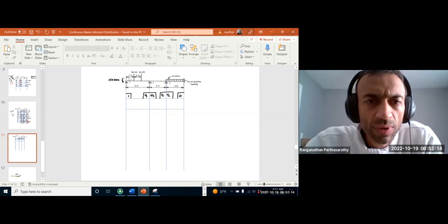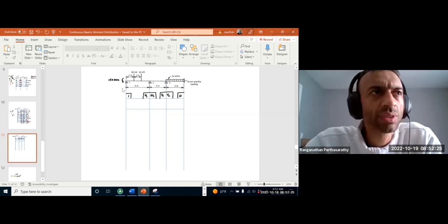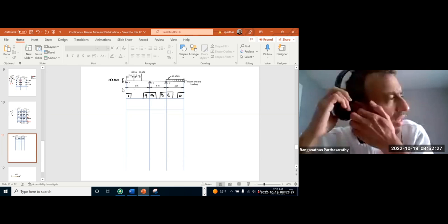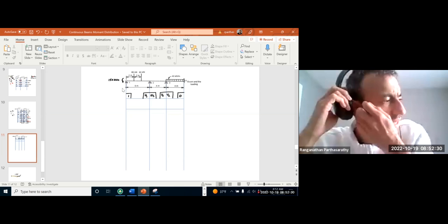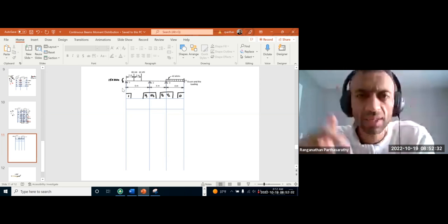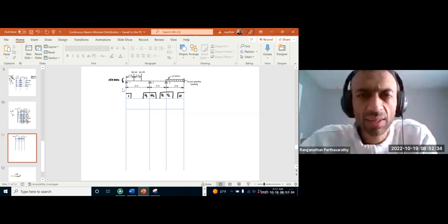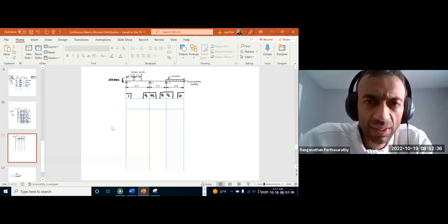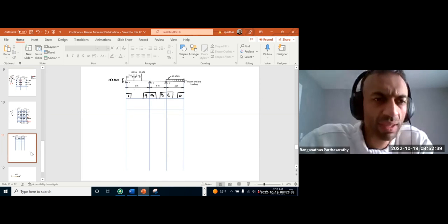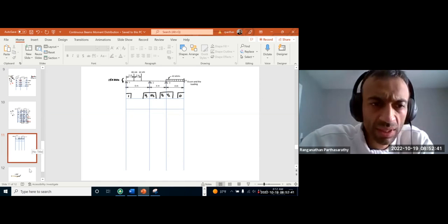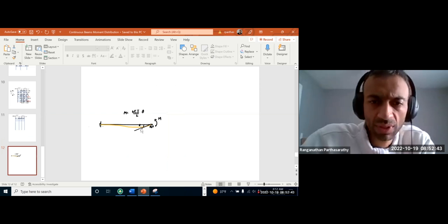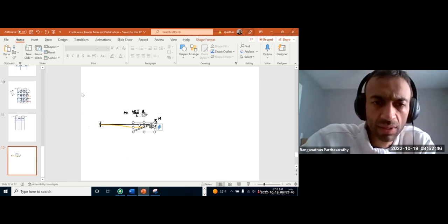Over here, we are taking this as a pinned end. So when we apply 80-80, that is for the fixed case. Since we are not taking this end as fixed but as pinned, it is better that we adjust in the first step itself. Instead of fixed, we take it for fixed-pin. So let's do that in a separate case and then put those numbers. That will be easier.